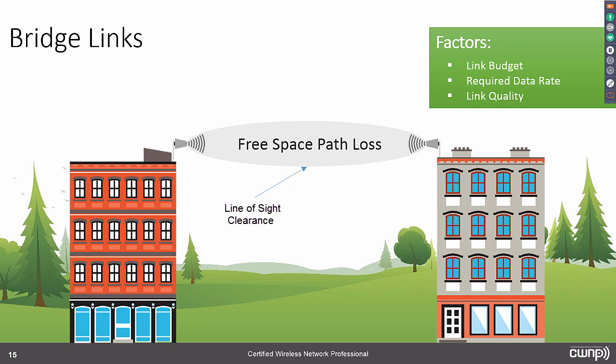specific data rates we can go to, and we go to those data rates by changing the modulation encoding scheme that we're using. Okay, so that's important to understand. Therefore, I need the signal quality required in order to use a particular modulation encoding scheme. That's really what I'm doing when I say I need this data rate. I'm saying I need the signal quality required to be able to do the modulation encoding that gives me that actual data rate.